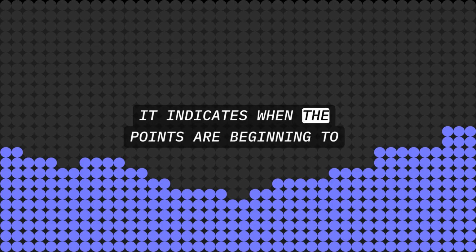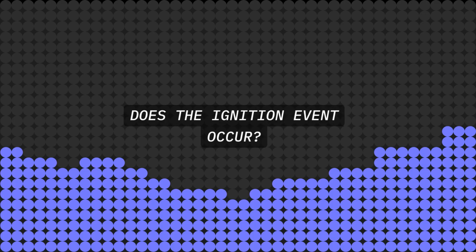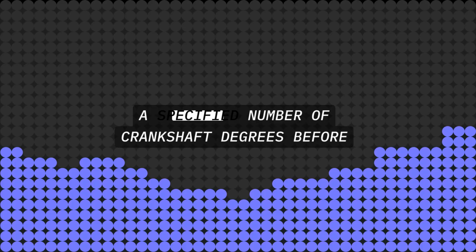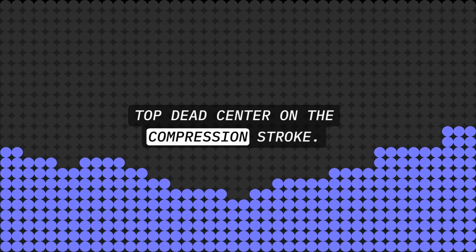It indicates when the points are beginning to open. In terms of the engine crankshaft position, when does the ignition event occur? A specified number of crankshaft degrees before top dead center on the compression stroke.